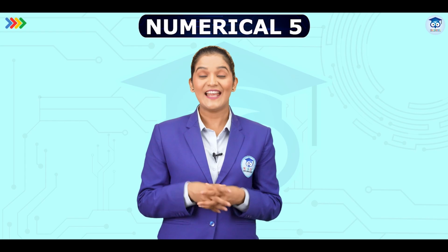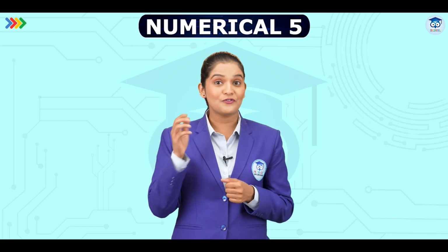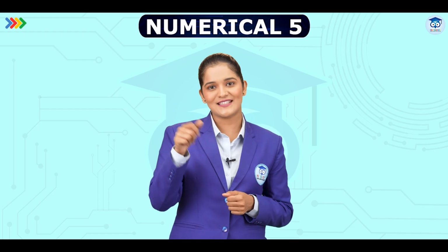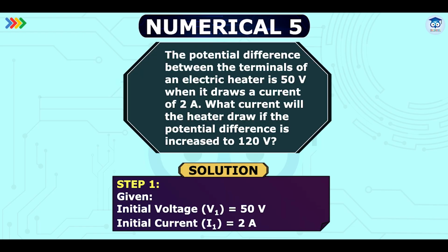Let us now solve the fifth numerical by breaking it down into clear and complete steps. The question states, the potential difference between the terminals of an electric heater is 50 volts when it draws a current of 2 amperes. What current will the heater draw if the potential difference is increased to 120 volts?